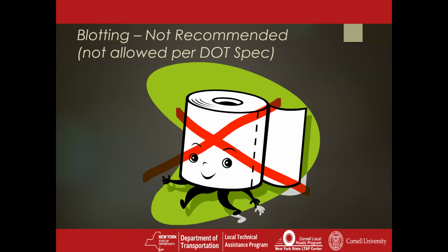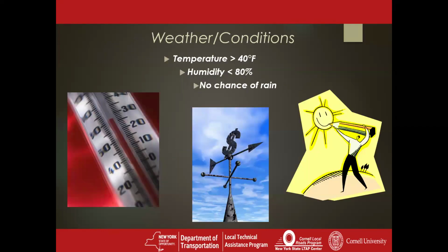And the crack sealer wasn't advanced enough, so it was sticking to the tires, even as it was cooling. So now it's over the top of the crack. Not a good idea. It makes quite the mess for your brand new project. So definitely not recommended and not allowed per our DOT spec.